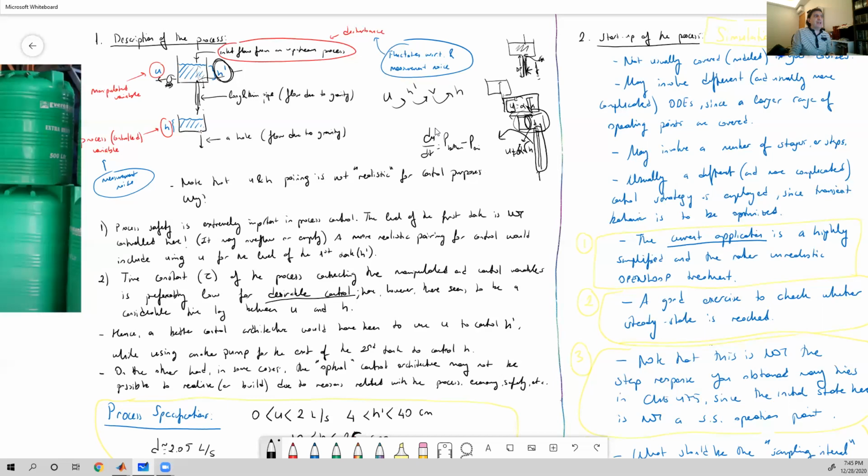So it's going to be just the pressure of the water height in this tank, and the net pressure inside here, and there is also going to be the frictional loss, which is related to velocity or velocity squared. So there's going to be an additional differential equation here. Maybe the details are not important, but understanding the additional mechanism, or the reason for an additional lag, is important to understand the process.